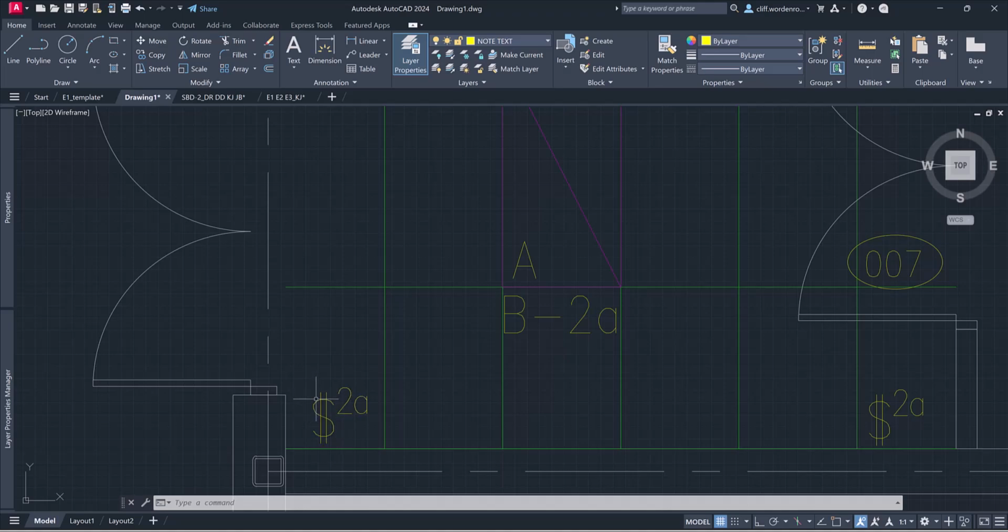So here I have a light switch. I have 2. It usually means I need 2. I'm going to have 2 switching stations. Even though I have a number in front, like a 2A, I'm still going to have 2 lines. So if I had 3 light switches, I'd have 3 lines and so forth. So the number 2 here means there's 2 light switches that control the lamps in the room. And the A means that it's controlling all the A lamps.